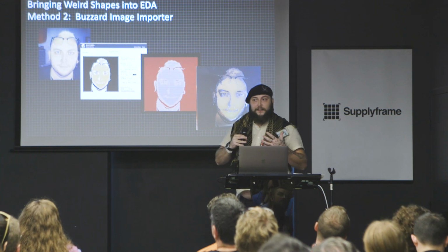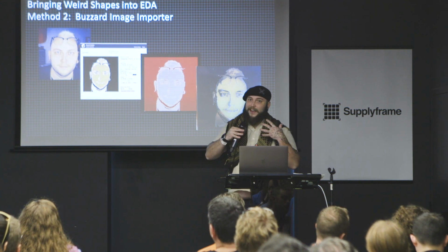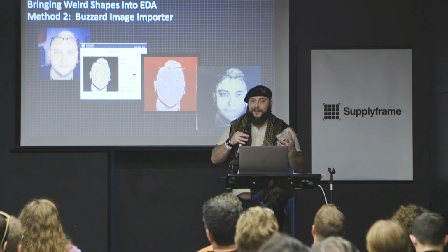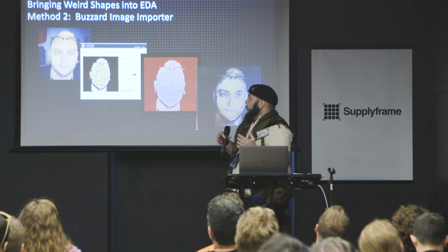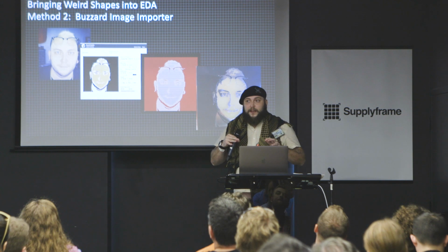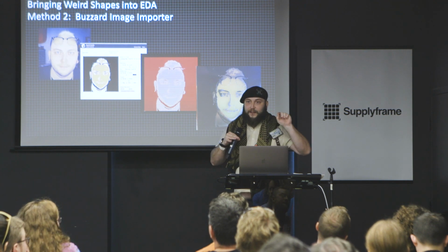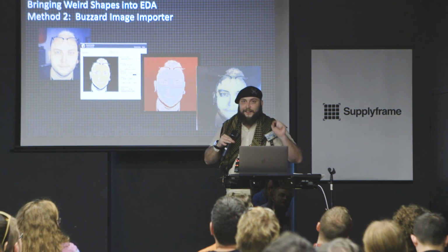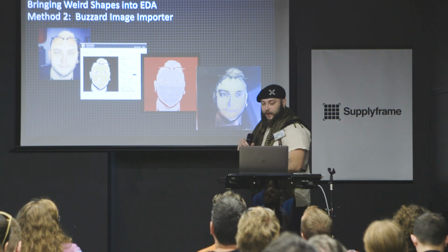So it makes it really easy to deal with, because a lot of the time you add art at the end of a PCB project because it gets in the way of everything else. With this, it's a little bit easier to deal with because you have one origin on that footprint, right, where you're not going to accidentally select it when you're moving stuff around.